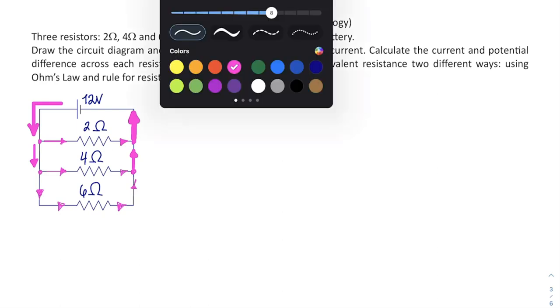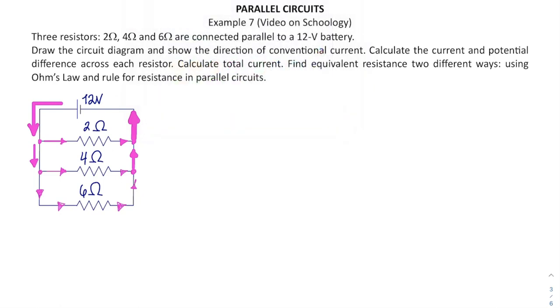So again, since we're pretending this is an ideal parallel circuit, no energy is lost on the connection, meaning all those wires, and I can just say that this guy has 12 volts, that guy gets 12 volts, and the last resistance doesn't lose anything and gets 12 volts again. So for total current, I could figure out resistance first and then go for total current. Or I can get separate currents, and that is what I'm going to do because that's simply easier.